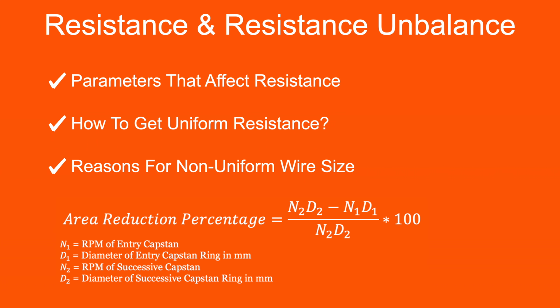In order to have uniform results of resistance, we should be able to get uniform diameter of wire with clean surface. That means the wire surface should be free from copper dust, dirt, and scratches. Now, how to get this quality of wire and what actions are required to be taken by us, I like to explain.